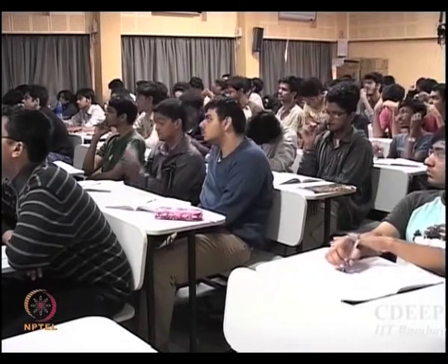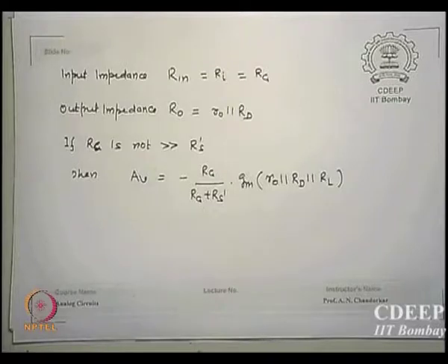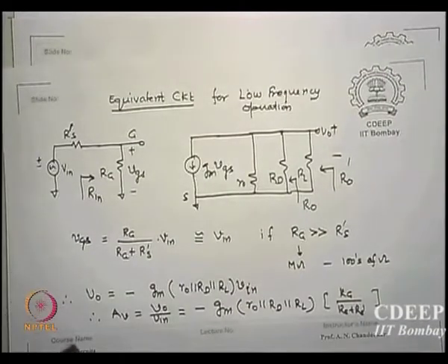Okay. There are two more parameters of interest, as I say, the input impedance and the output impedance. Before we show it, I will give detail how to calculate for any network. I think you must have done it. If you are given a network, you can always find the output impedance and the input impedance. How do I calculate these impedances? Short the outputs, and from the input side apply an input source with the input resistance Rs, you can even make it 0. Whatever current comes out, Vx by Ix is the input impedance.